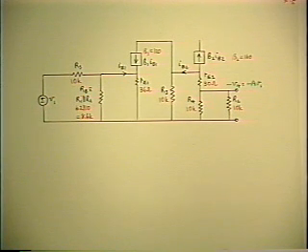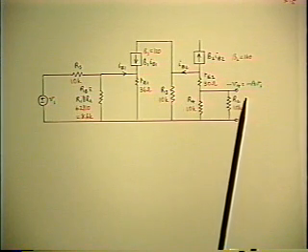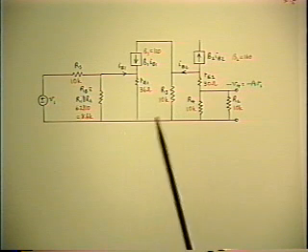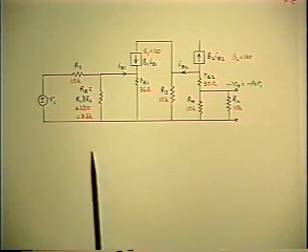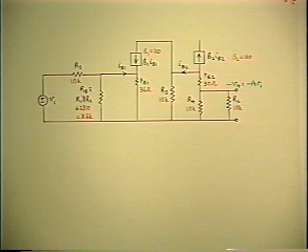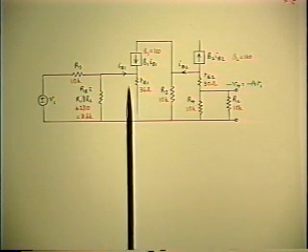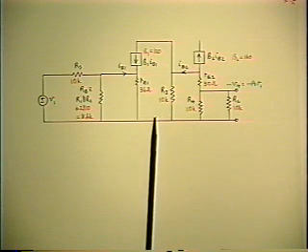And once again, you've got a wide range of choices about which techniques to bring to bear on this. Some of them involve circuit reduction by doing the algebra on the diagram. Some of them involve techniques like reflecting emitter resistances one direction or the other. Some of them involve current and voltage dividers. Some of them involve strictly algebraic techniques. You take your choice. So I'll select a particular sequence just as an example.